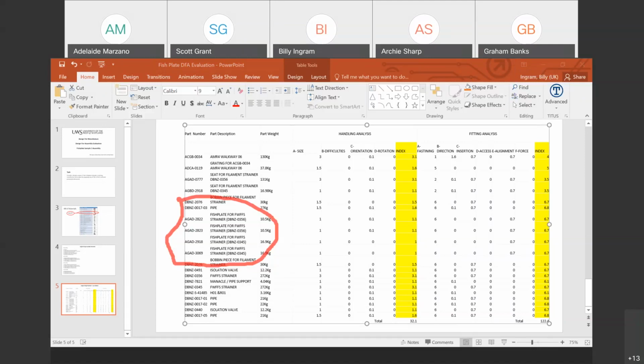It gives you a description as to whether you can manhandle it and lift it in yourself, whether you need a two-man lift, whether you need possibly a hoist to lift it in, or the opposite way, whether it's extremely small and you need specialised tools to handle it, which is also penalised because it's specialist installation. So the size just came down to going to the weights and seeing whether we could do a one-man lift, a two-man lift, or whether it was going to have to be a crane or a chain block lifted into position.